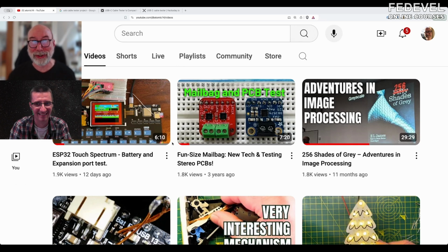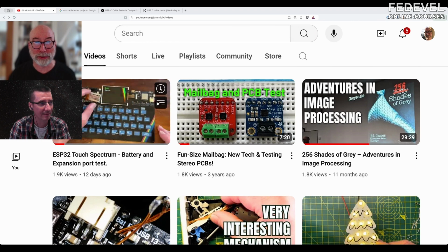This is actually doable. 13 touch pins will give me 40 keys. So I can actually do 40 keys, which is exactly the number the Spectrum needs. So my initial version was just a matrix keyboard using 13 touchpads and the color silkscreen printing.